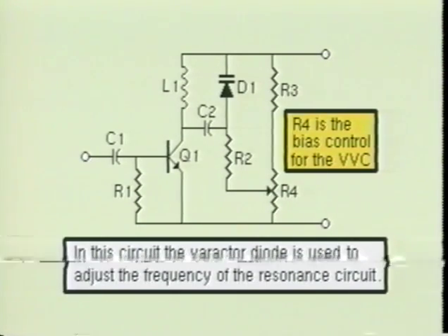When the diode is reverse biased, the depletion region will become depleted of majority charge carriers, which causes the depletion region to become a poor conductor. This depletion region then acts as a dielectric material. The width of the depletion region will be proportional to the applied voltage. Therefore, the capacitance of the varactor diode will be inversely proportional to the applied voltage.